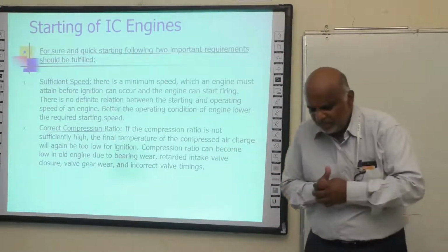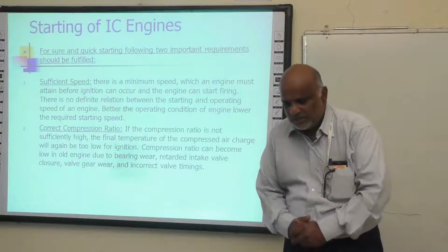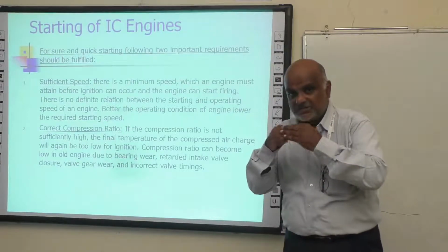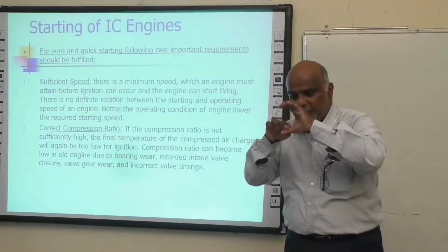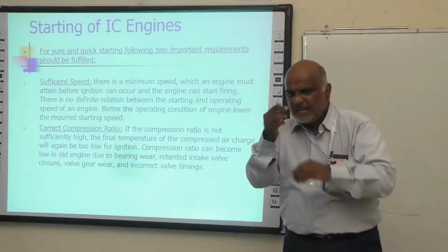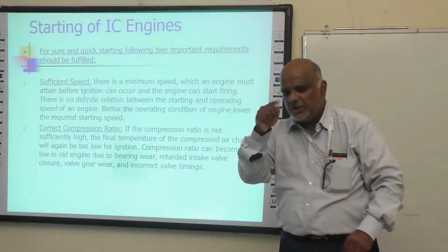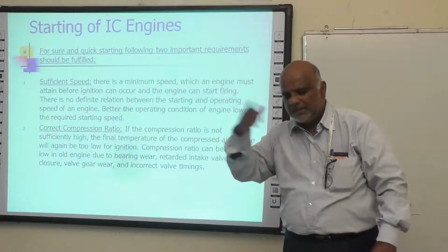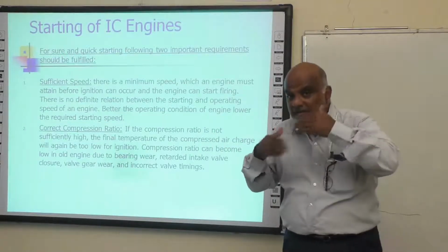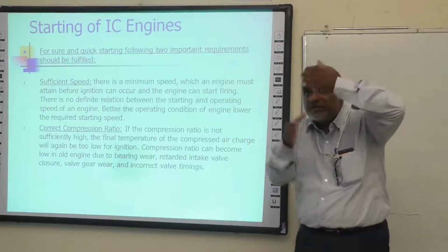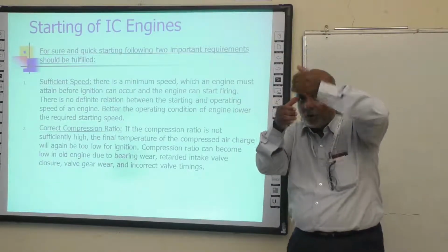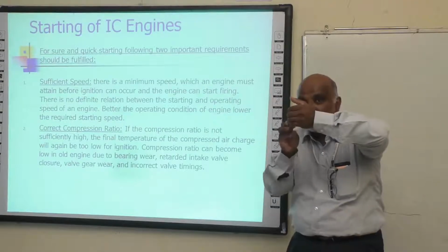In a brand new engine, the clearance between the connecting rod and the crank pin, if you check it with a feeler gauge, will be within the limit of around 0.12 millimeters and so on. But as time goes on, there is wear and tear in the bearings. So the piston with the connecting rod drops down a little bit because of the wear.